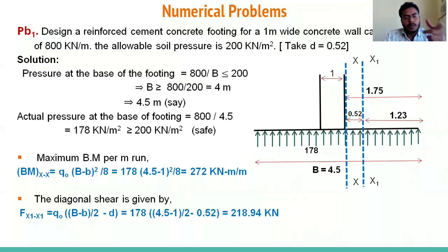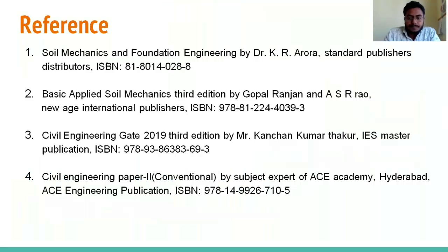We have to calculate on this value also. From the geotechnical engineering point of view, we have to do this much only: calculate the dimensions. If you are designing the foundation, then on the basis of the maximum bending moment we have to calculate the reinforcement and check whether the effective depth is safe or not. We have to design the concrete, so there are various other procedures, but from the geotechnical point of view we do only this much. These are the solutions that I have taken.